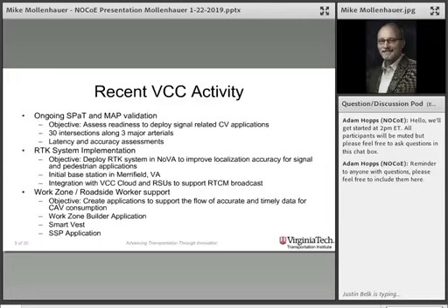We have done some accuracy assessments, some field observations, and collected data to understand, with a corrected GPS versus a non-corrected GPS, what the differences in accuracy are. We've done a first round of data collection, and we've shared those results with VDOT, but we have not yet published anything. We hope to have a second paper coming out on that at the end of the first quarter that will discuss what accuracy we're actually seeing and what the benefits are of having that RTCM broadcast in place.